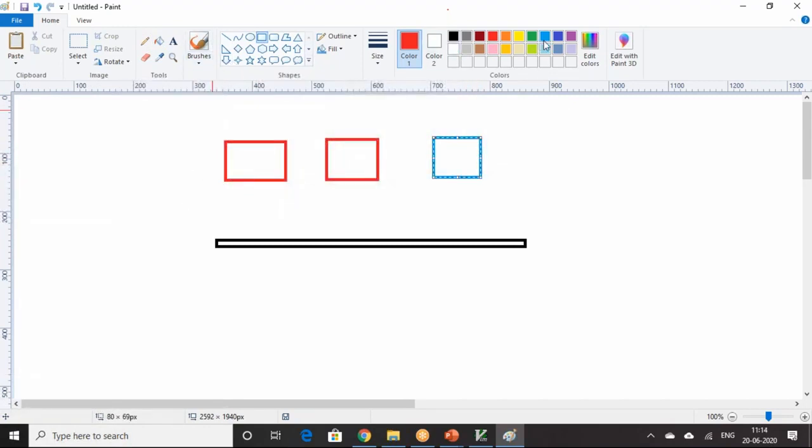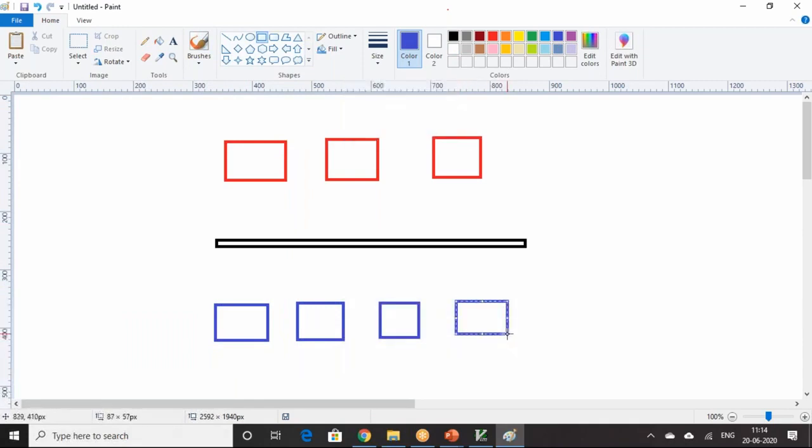And let's say a few slaves. These are connected to the interconnect. This protocol will be the AHB protocol, because these are all AHB based components. Their communication with the external world happens through the AHB protocol.